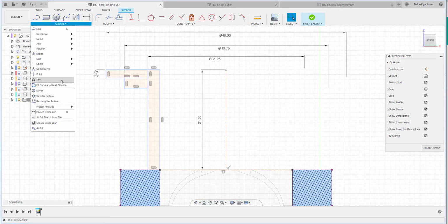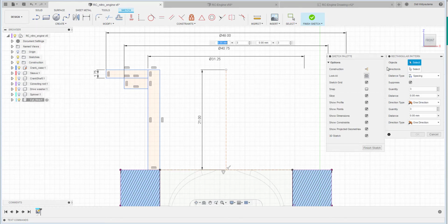I want to continue to the rectangular pattern for this object, this one, this one, this one, and this one, not the long one, sorry, just the shorter one, that one. The direction, I reference to this line, and I use a spacing with the number of instances as 5.